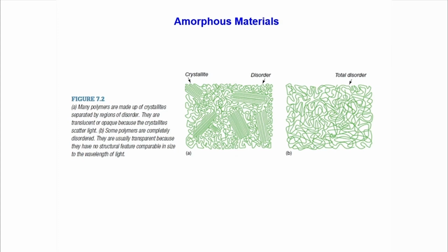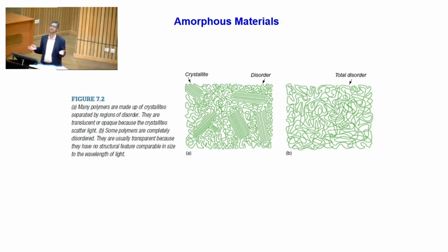Now, dislocations cannot be thought of there, because the concept of dislocation is only valid for ordered arrangement of atoms, because you're thinking of a slip plane, an extra plane, movement of these dislocations. That's only possible when you have a completely ordered arrangement of atoms. In a disordered arrangement of atoms like an amorphous structure, you cannot think of dislocations. The dislocation concept will no longer be valid.